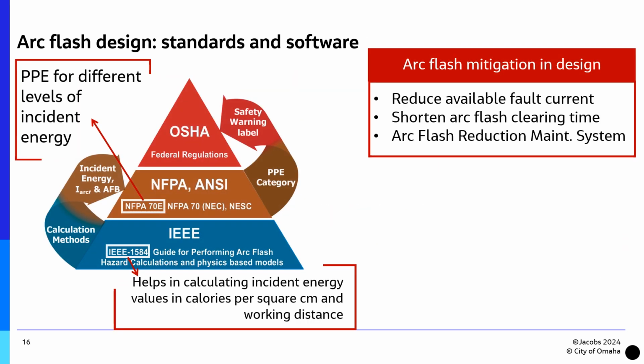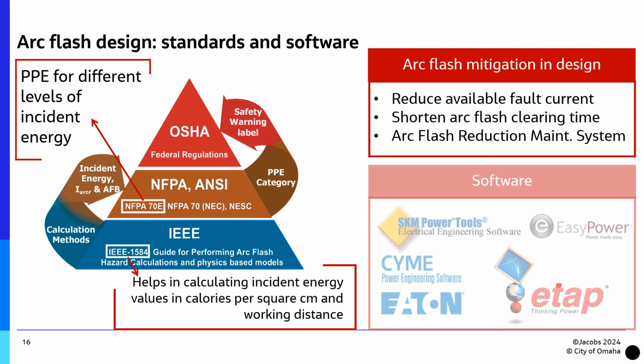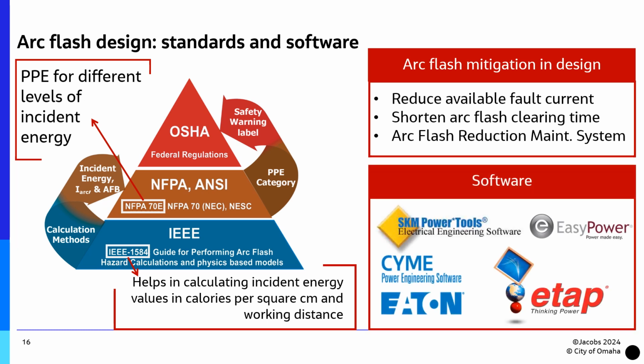The NFPA 70E standard helps us understand what PPE operators should wear, and the IEEE 1584 standard helps in calculations. When used in design, this can help reduce fault current, shorten arc flash clearing time, and enable an arc flash reduction maintenance system in a variety of design software.